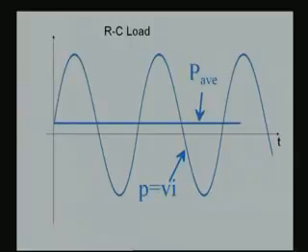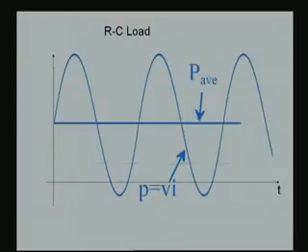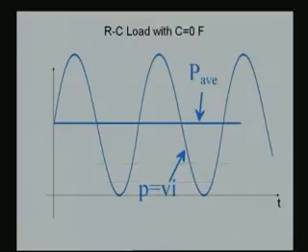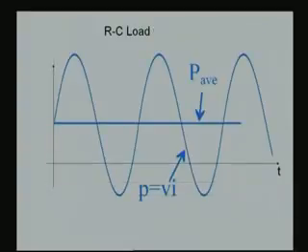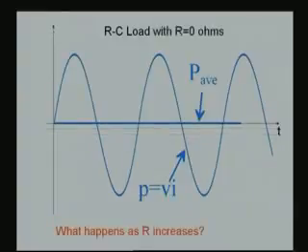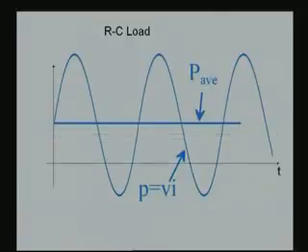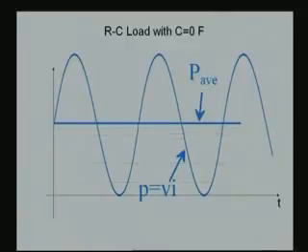As you start increasing the R, the average power keeps increasing till at a point when the R value becomes so high that it swamps out the impedance provided by C, that it emulates a pure resistive kind of circuit as though there was no C. So, here again, when R is decreased, it goes towards average power equal to 0, and as R is increased, it goes more and more towards having an average power.